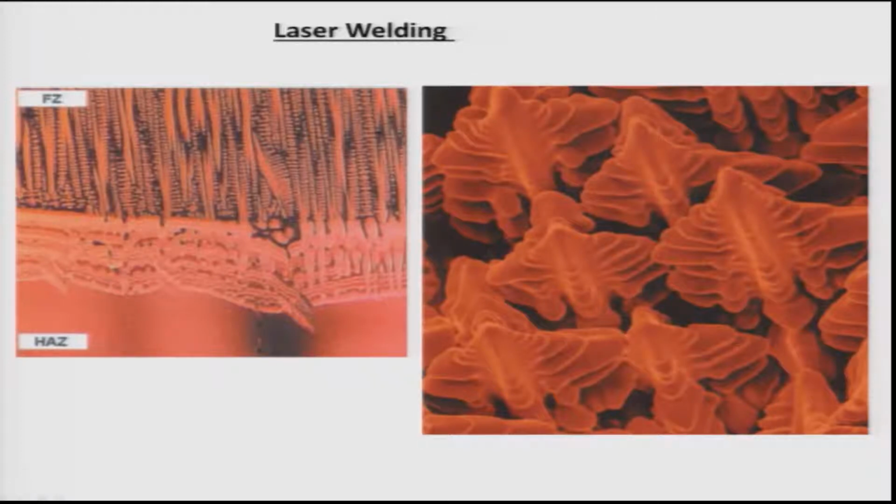Okay, those we will discuss later on. Dendrite is a tree-like structure, and this forms at the interface between the solid metal and the liquid, and then it grows inside the liquid. So the basic aspect is how these dendrites, which are shown in a bigger picture here, these are the dendrites of a nickel-based superalloy growing into the melt, how these actually grow into the liquid. That's the question we need to understand more.